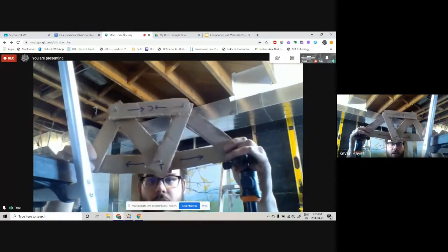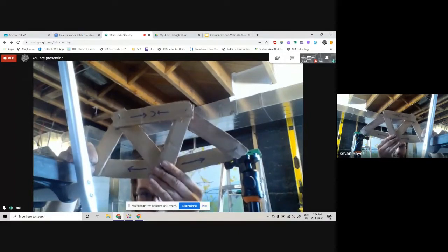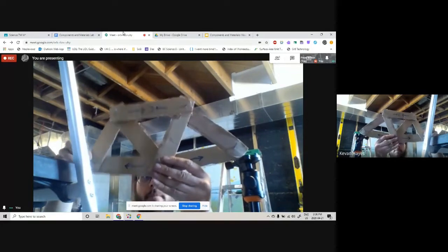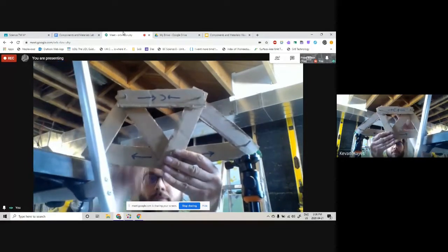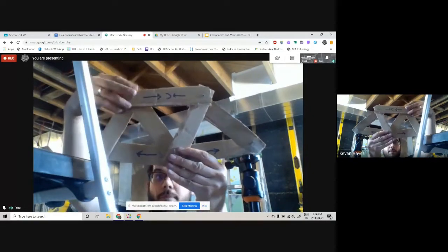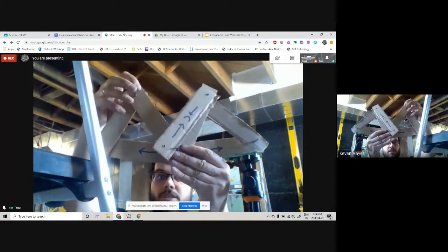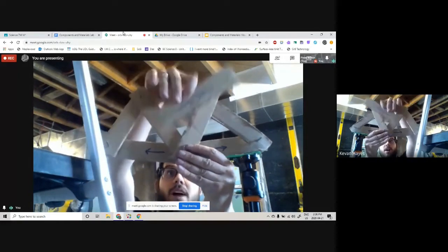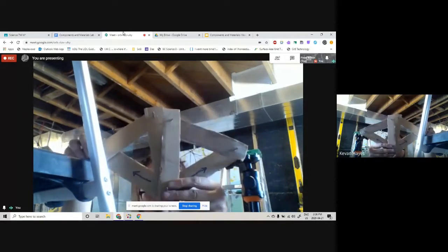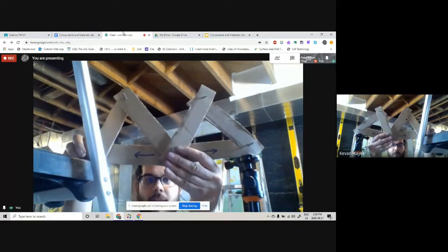And here's how we know this. If I try to hang something from here, if I pull downward on this, the truss doesn't move. But if I take this top component off, this top member here, the one that I've labeled with a C, that is experiencing compression. If I take that component off and move it out of the way, now if I pull down on the middle of this, immediately this truss fails. You can see that these two top parts move together.